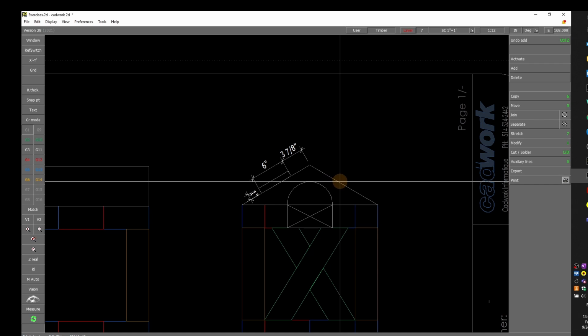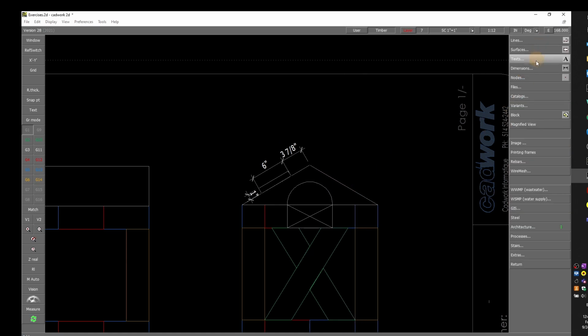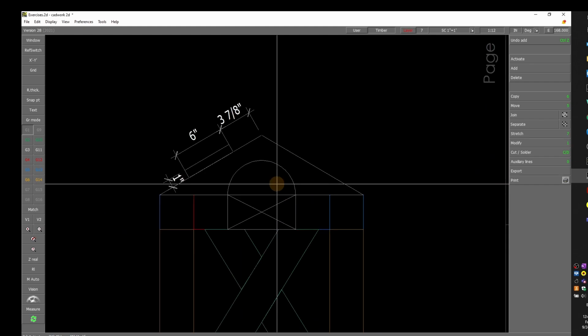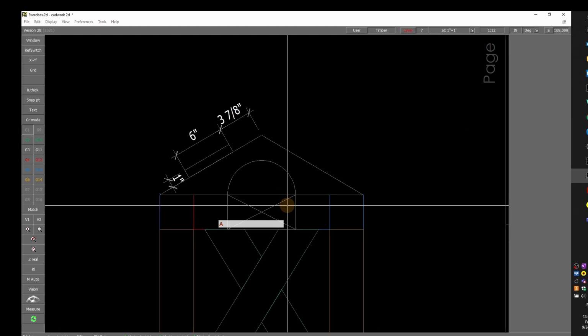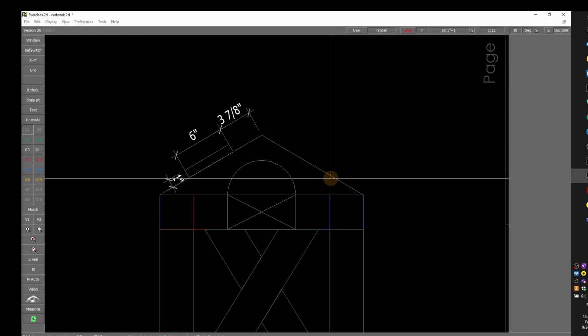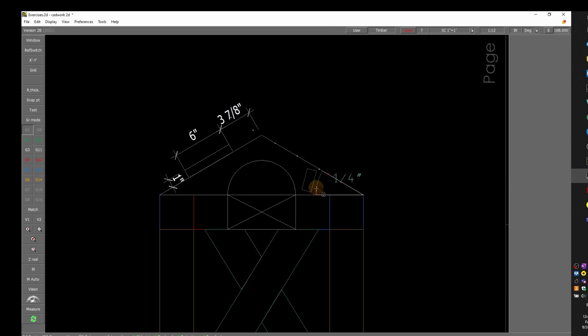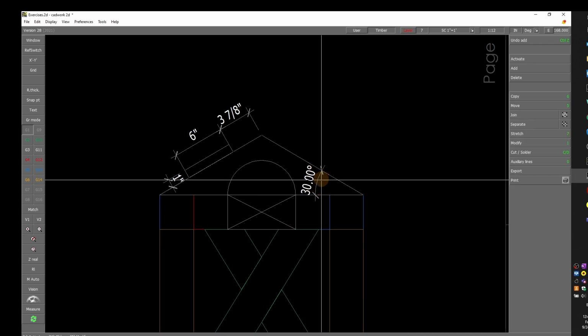Then I'd like to know the roof slope. So for the slope, it's an angle dimension. So add dimension angle. The shortcut is A. And for roof slopes, there are different options. So as soon as you press A, you see that, well, I could pick 2 points, 2 segments. So it gives me the slope between 2 segments.